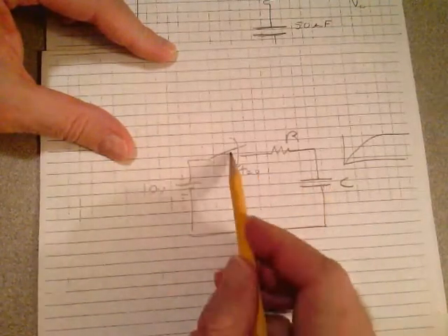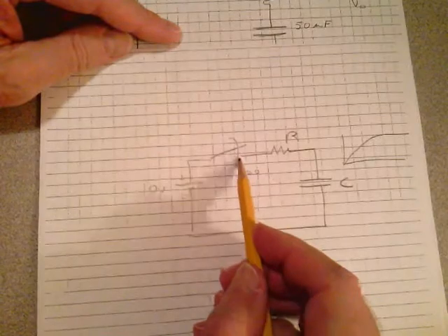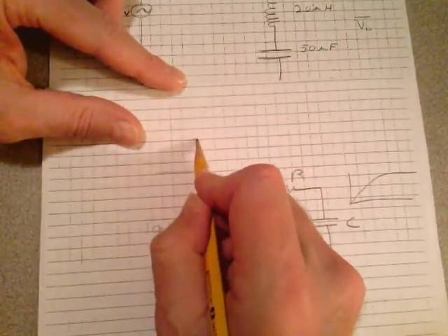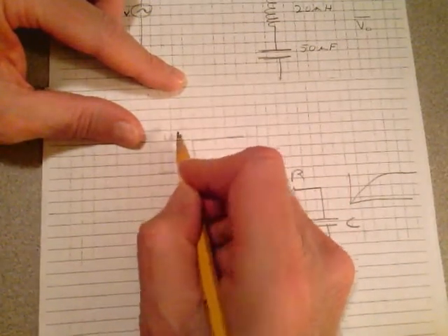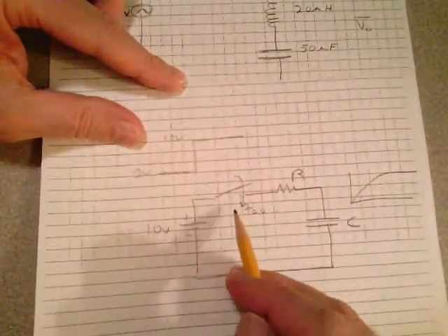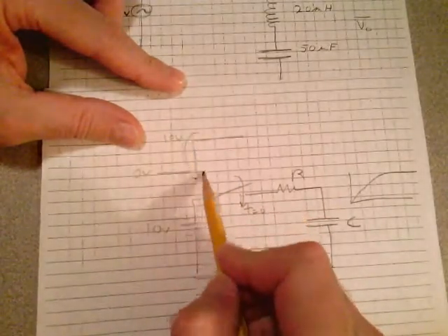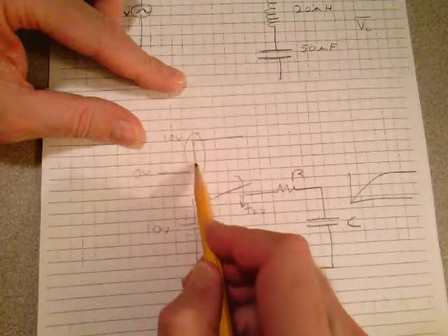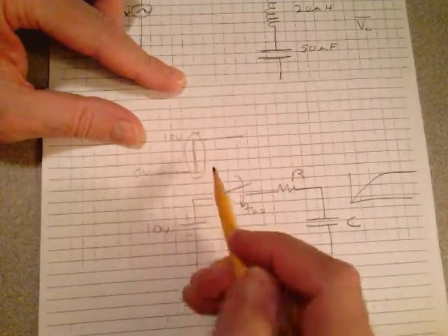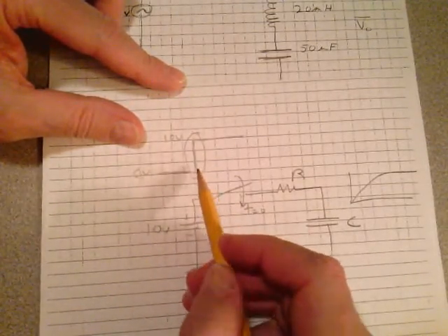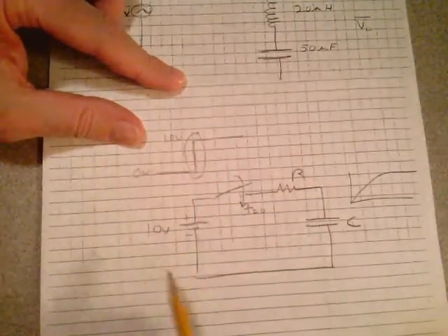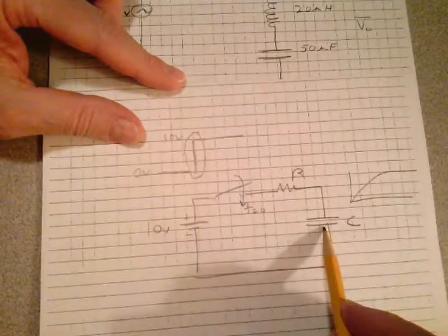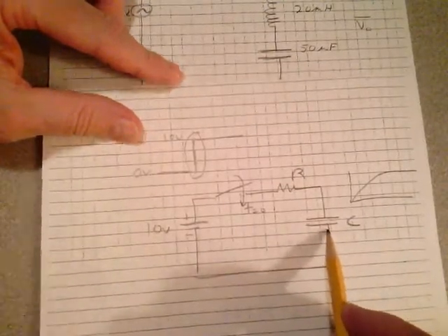Well, what does the voltage look like at this point when you close that switch? It looks like a step, a step function from 0 volts to 10 volts when you throw the switch. There's a lot of high frequency in that step. In a Fourier analysis of that step function, there's a tremendous amount of high-frequency sinusoidal waves that make it up. So at a very, very high frequency, you know that capacitor looks like a short circuit.